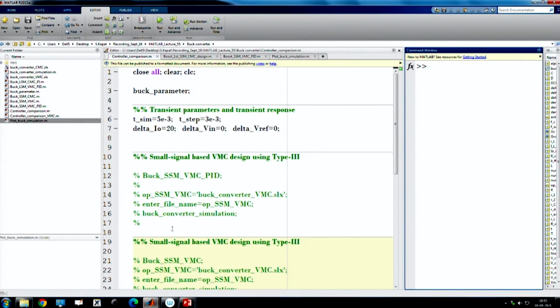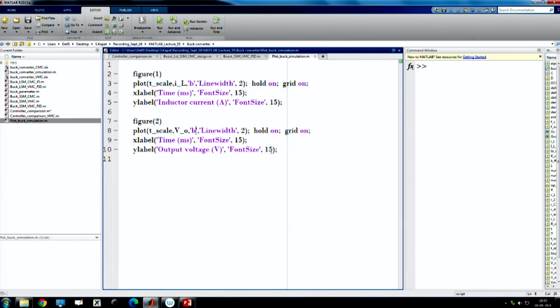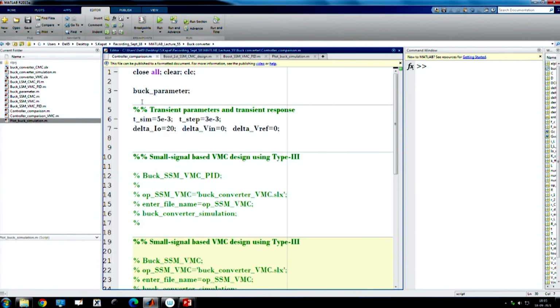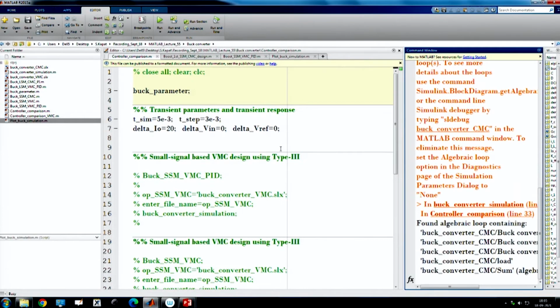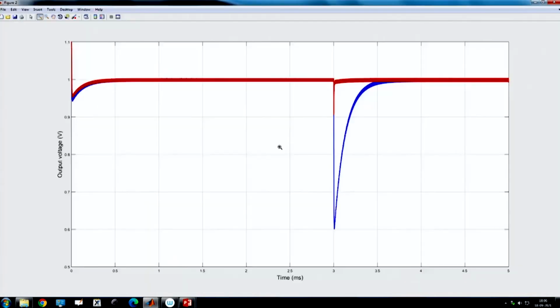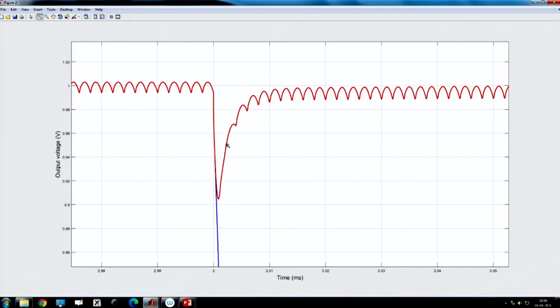Now, if you consider on top of that load current feed forward, that means we are considering 1, and we are using a different color. Let us say we are using red color, and let us run it. So here also we are using 500 divided by, so let us go 110, and see, it is much faster because we have incorporated the load current feed forward, and we have discussed the load current feed forward can drastically improve the performance, right.